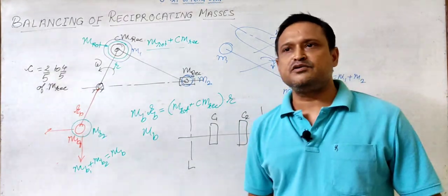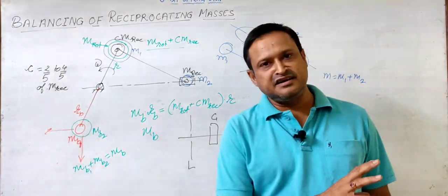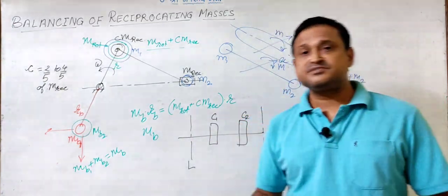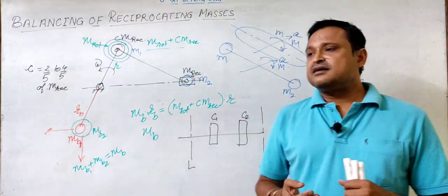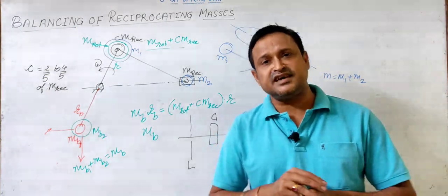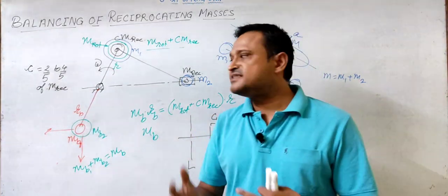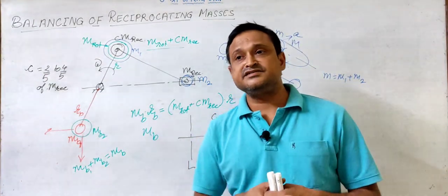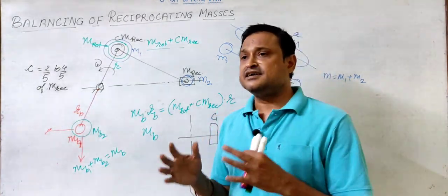Here we are finding out the required balancing mass in the system, but such systems are getting only partially balanced. When these residual unbalanced forces, dynamic forces, are there in the system, they do affect the system, right? So what can be their effect, we will try to understand with the help of the effects of partial balancing in locomotives.